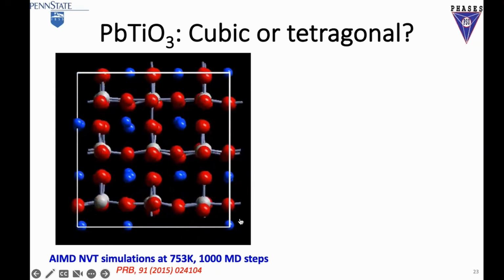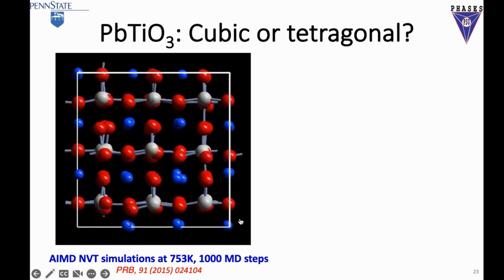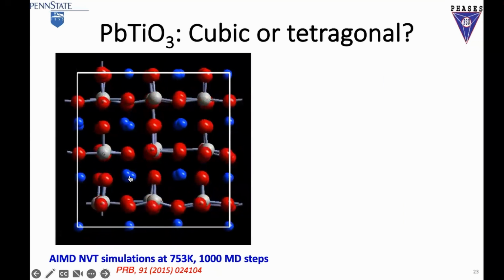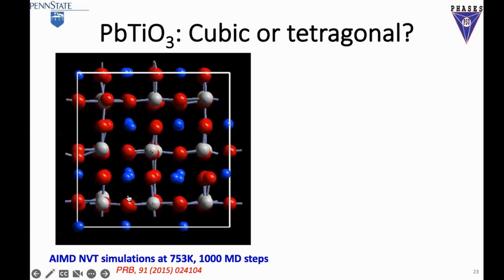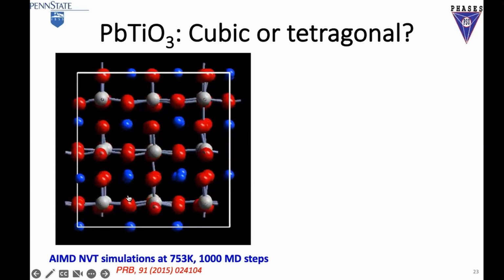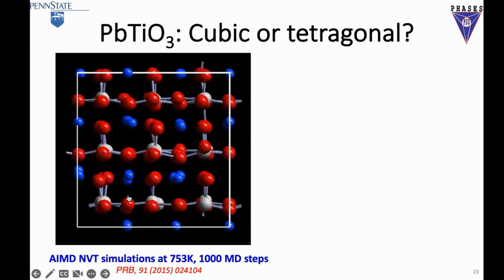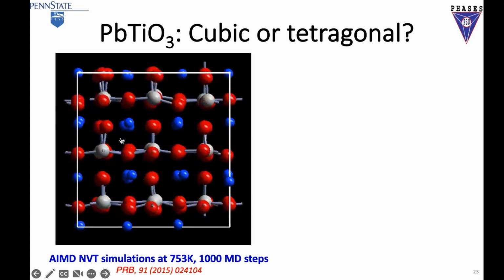So we take the white, the cubic, the c/a ratio is cubic. That means for X-ray, it sees c and a. However, what is interesting is that the blue ones are the titanium. You see the titanium atom moves up, moves to the right, moves down. So this is the process across the central point. You have central symmetry, but it doesn't stay there. It goes over and then goes that way, right? Of course, we know that if this titanium goes up, that titanium goes down, what do we have between the two? They cancel each other, that's right.